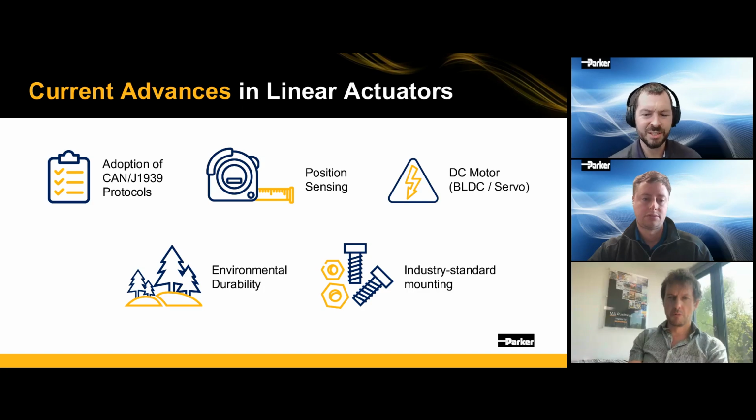And additionally, industry standard mounting. A lot of our applications for mobile hydraulics obviously already have some type of hydraulic cylinder on them. And a lot of EMAs and EHAs have very special base and rod mounts. So you might have to make pretty severe design changes to your mechanism if you're going to retrofit an EHA or an EMA into an existing hydraulic cylinder application.